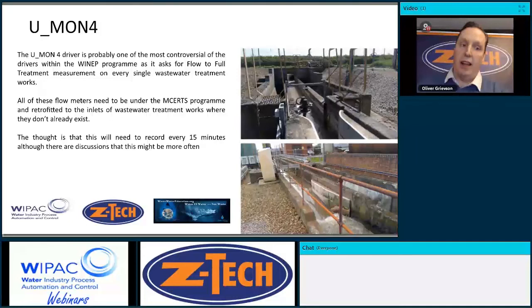UINF 5, improving that FFT to DWF ratio. UINF 6, improving storm tank size. So if I quickly go into UMON 3, the U drivers are part of the Urban Wastewater Treatment Directive, and the monitoring drivers are basically there to give us knowledge of what's going on. We don't man our works in the UK all the time, so when people aren't there, we have to have monitors to discover what's going on.